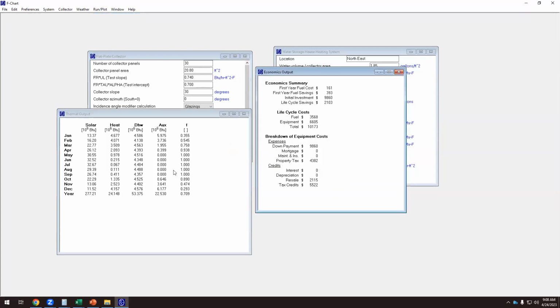But we can say, okay, let's put like 30 panels. Okay, so in winter we go up to 35% of the needs, but that means that it's dangerous and we have overheating. So if we have a pool, we can allocate all this energy into the swimming pool, that's good. But if we don't have a swimming pool, or if we don't have a way to get rid of this excess of energy, that will harm the system. It will burst because of the overheating.